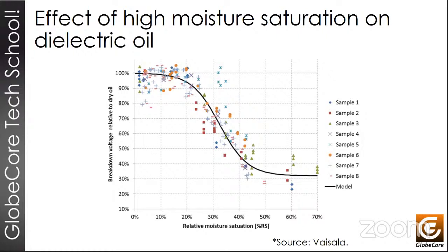They used online measuring equipment that allowed them to know specific changes that occur in the oil characteristics, and they were able to measure and determine this curve of the breakdown voltage as a function of the relative humidity of the oil. And we can see that at low moisture levels and saturation, we get very good values in terms of the breakdown voltage in the oil. So when the saturation begins to increase, we can notice a significant decrease in that characteristic.